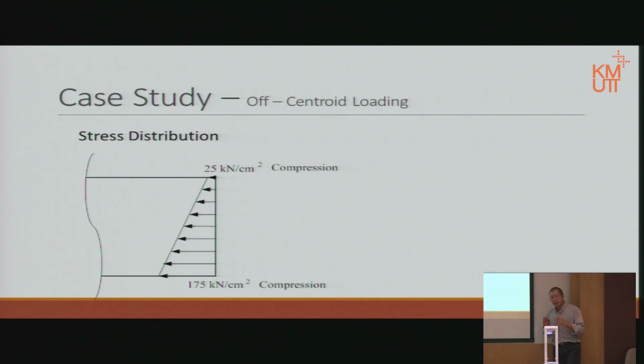Notice that the length of the beam has no effect on the bending moment, because this time the load is coming this way and the 90-degree distance is that way. Therefore, it is the same bending moment throughout the beam, for this case, of course. And that is the answer.